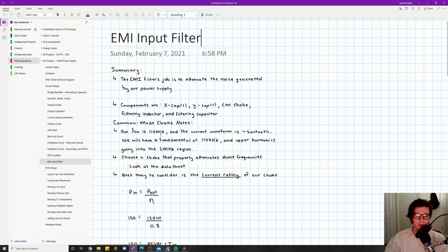Our switching frequency is 110 kilohertz, and the current waveform is roughly a sawtooth, some type of triangular-looking sawtooth wave. I think I covered something like that in that other EMI video I did, so go check that out if you want more information on what we're dealing with here. Basically, I'm trying to get an idea of what type of noise we'll be dealing with. We'll have a fundamental at 110 kilohertz with upper harmonics going into the 1 megahertz region, right? Hopefully that makes sense to you.